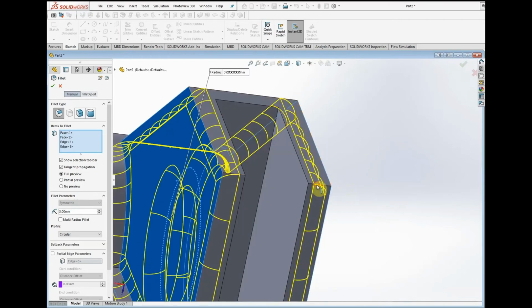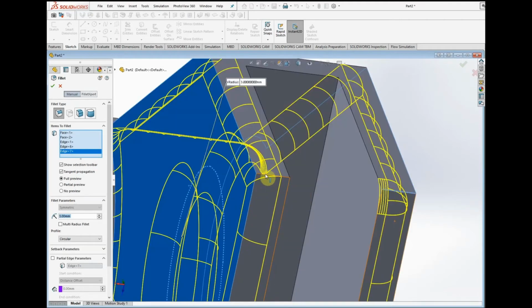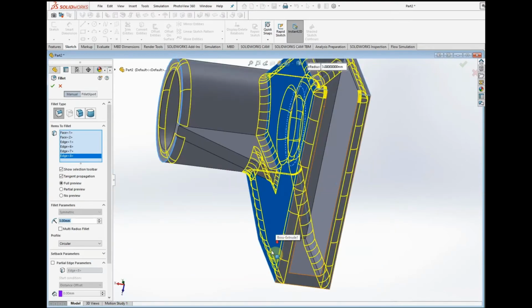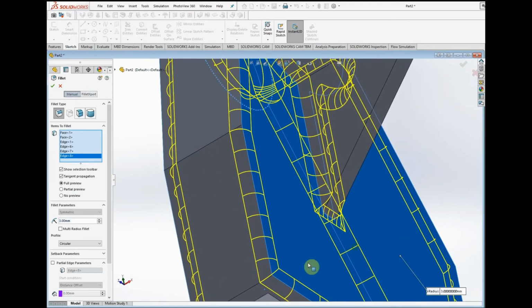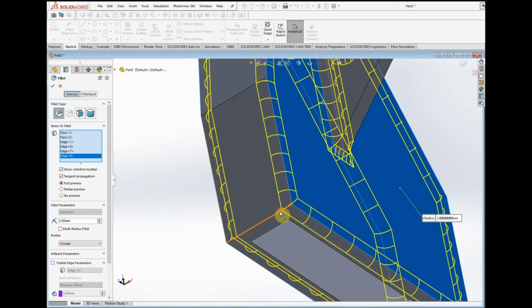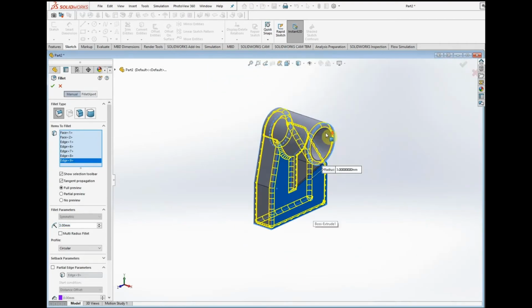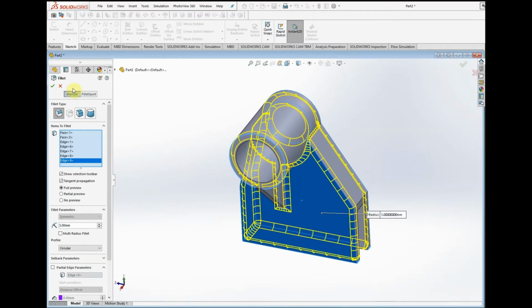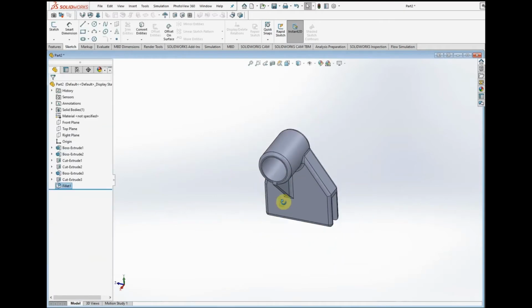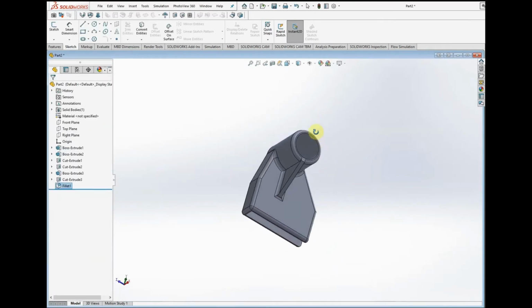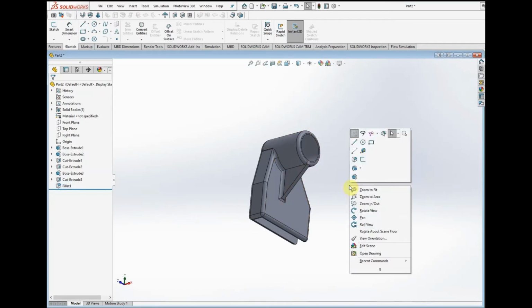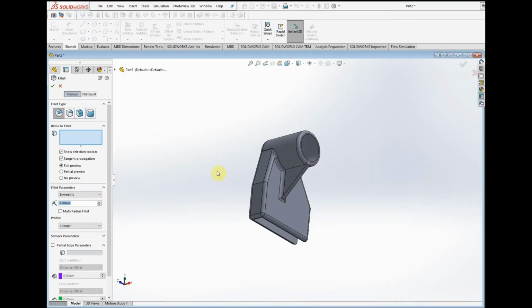I will get a little round down here on these corners too, and on the back there, just to, again, make it look less boxy, less square. The less sharp edges, the better. Yep, and we want something on that back line there. So we'll just try again with the fillet, and now it's in a separate feature. It'll probably, yeah.